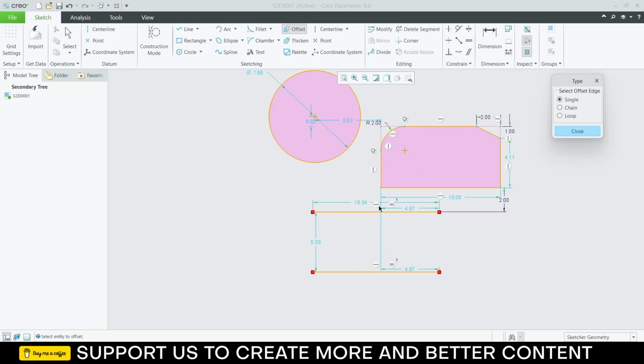So it created an offset of the line at a distance of 5. Looks good. Now close it. Now click on thicken. Let's try to see what this is. Suppose I want to make a rectangle but with circular ends. So how can I make it? It is something like offset but with advanced features. So I will click on circular.